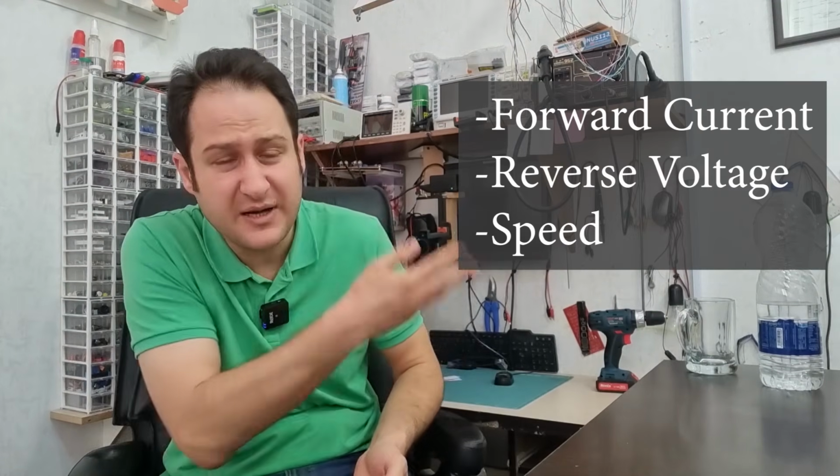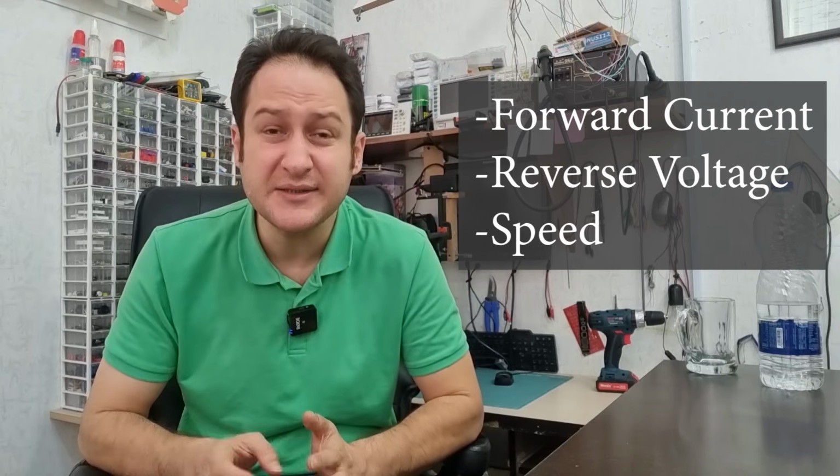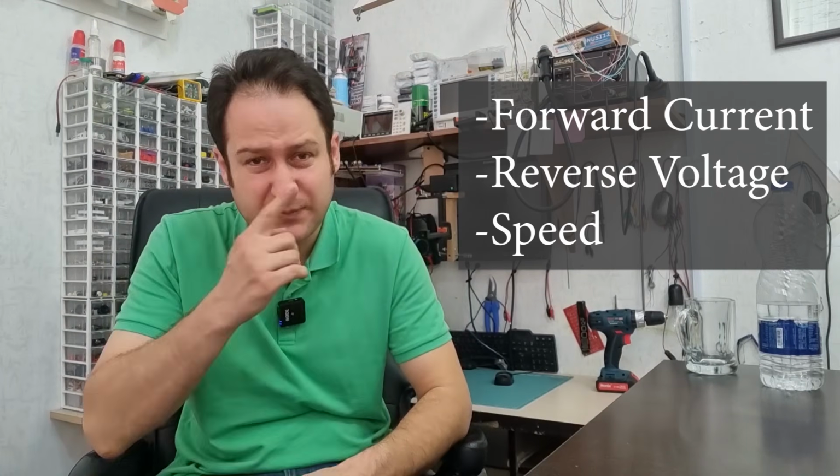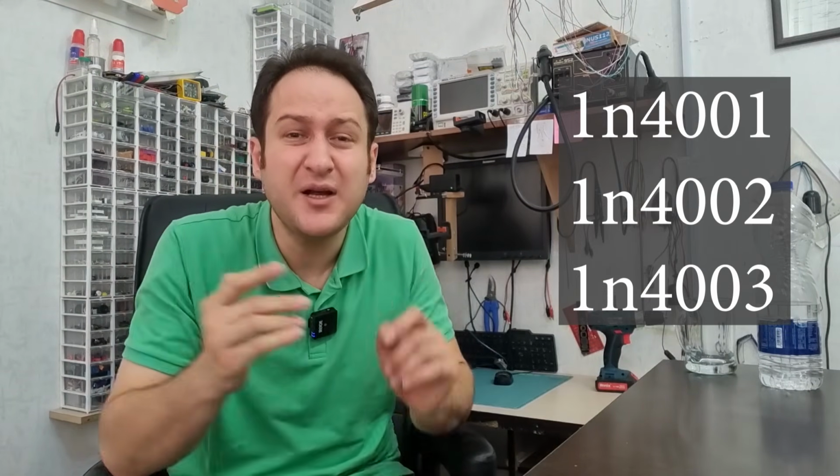It seems easy, but you have to be careful in selecting a proper diode. These are 3 important parameters to consider in selecting a diode. All of these parameters are available in the datasheet. In the datasheet of every diode, you can check how much voltage the diode will tolerate in a reverse bias setup. For example, if you are going to rectify AC power in the United States by a half-wave rectifier, you can use these, but you can't use these because of shortage of reverse blocking voltage.